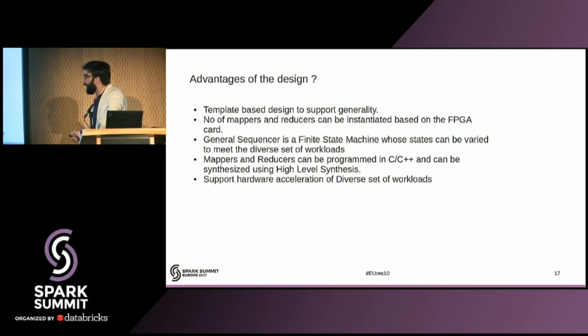Since the end users are big data engineers, we do not expect them to know VHDL or Verilog. So we are proposing that they use high-level synthesis and program the mappers and the reducers in C and C++. And because of the very nature of the design, it supports hardware acceleration of a diverse set of workloads.